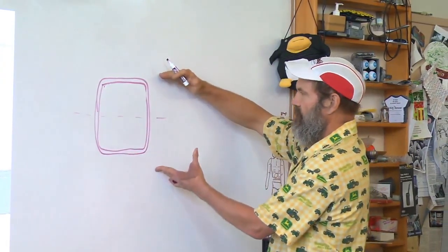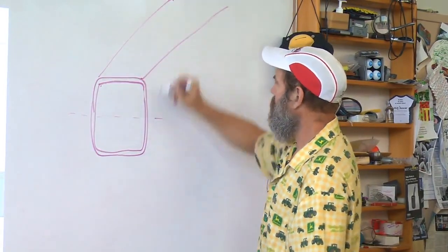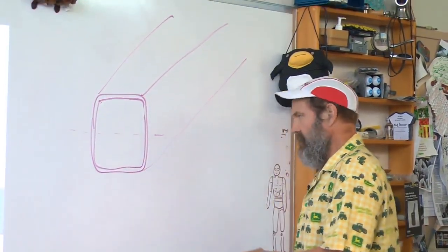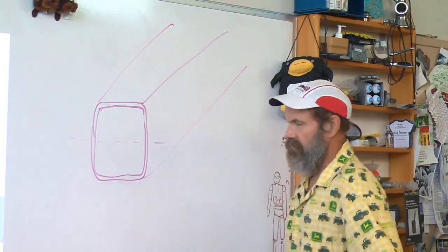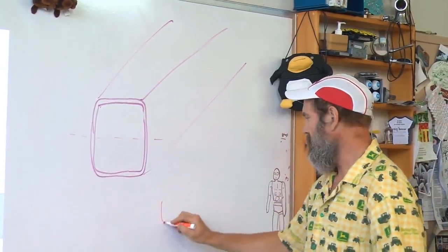So it's very stiff and strong globally, because I've put my area, my mass, far away from the neutral axis. Fantastic. Now I've designed this machine, for example, a bridge-type machine.